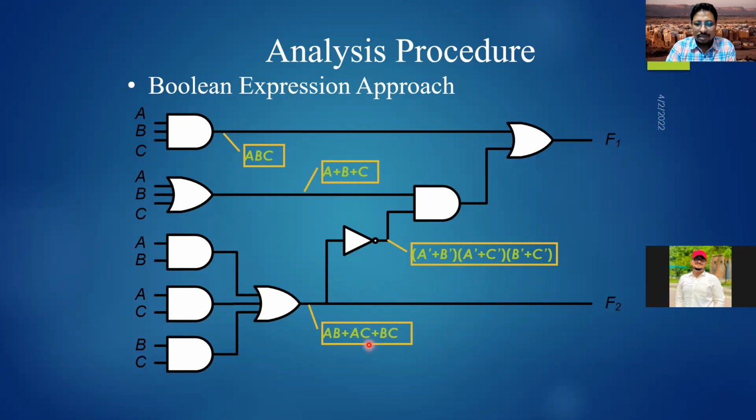The same thing. The third one, it's the ORing one between them. Again, first it was a sum of products. Now here it's a product of sums. You change it because here there were products, but among them were sums. So it was sum of product. Here now it became product of sum. This sum, this sum, this sum, but what is between them is a product. So it is a product of sum.